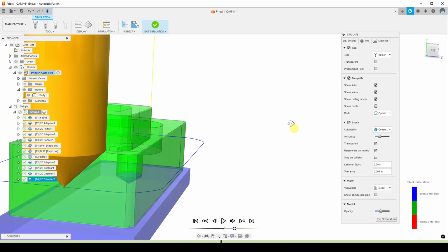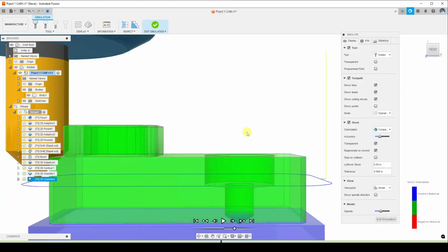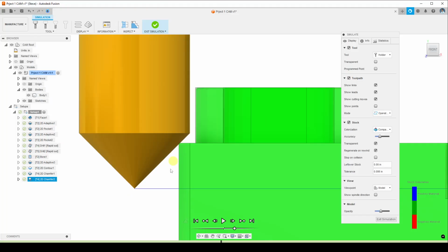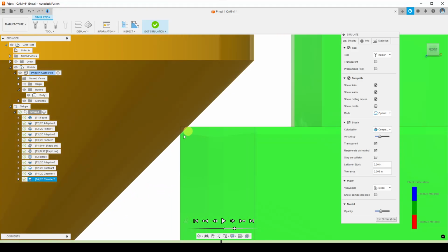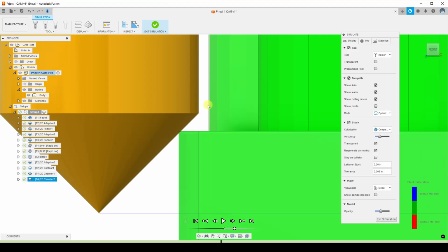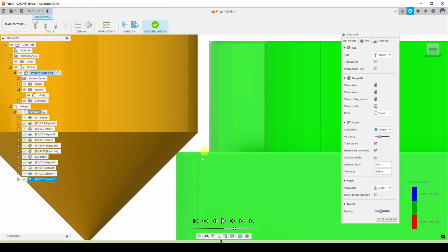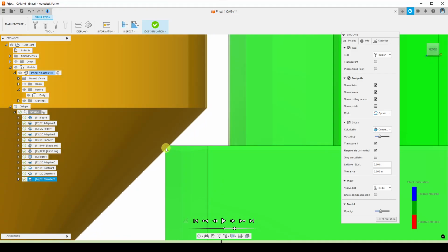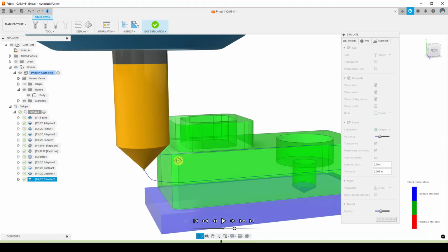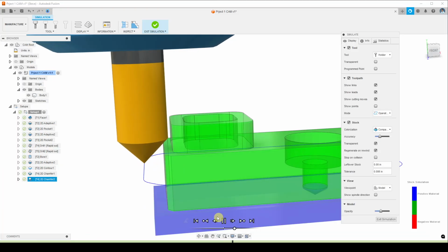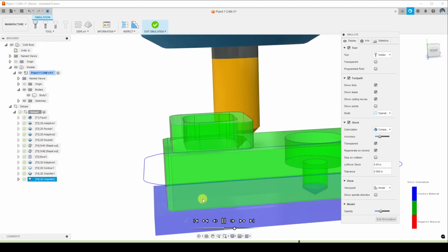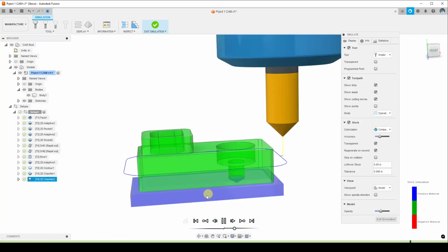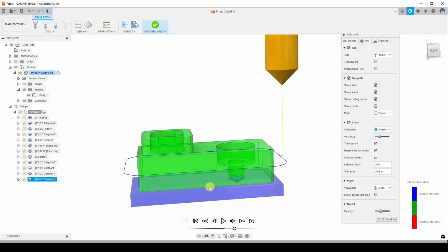So let's take a look at this from the side. All right, it looked like that was actually a great combination: 0.2 chamfer tip offset, 0.005 chamfer width, and 5 thou chamfer clearance. It let this tool get the cutting edge on that 90-degree edge all the way around without hitting any of the other parts. Okay, so that is it for all the toolpaths for this part.